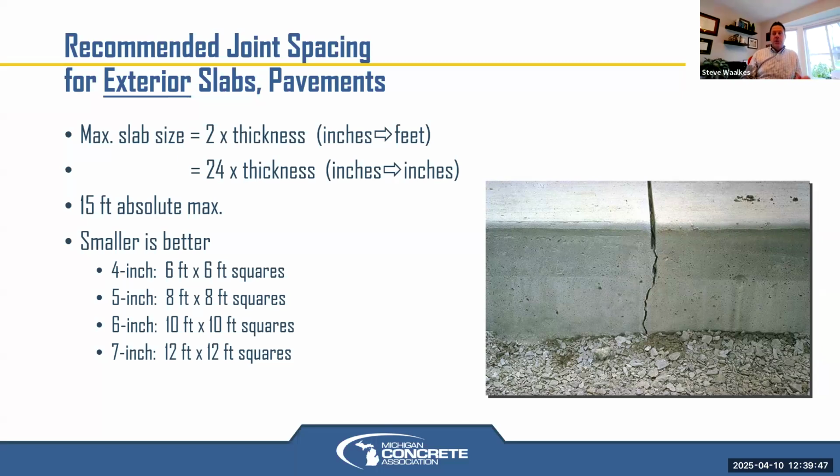If you're doing a 4-inch pathway trail, for example, Jackson County's done a lot of concrete trails and pathways recently, 8-10 foot. If they go 4 inches, they could probably do the 8-footers with 8x8s. But if it's 10-foot wide and they want to keep the 4-inch thickness, you probably have to go 2 5-foot slabs and do 5 foots to do that concrete trail or multi-use path, whatever you want to call it.